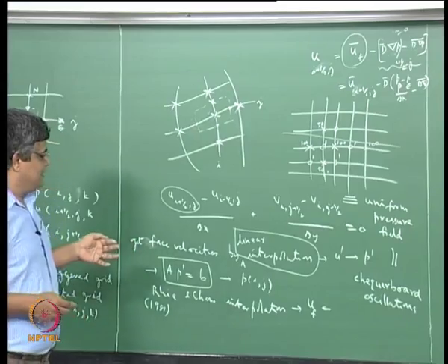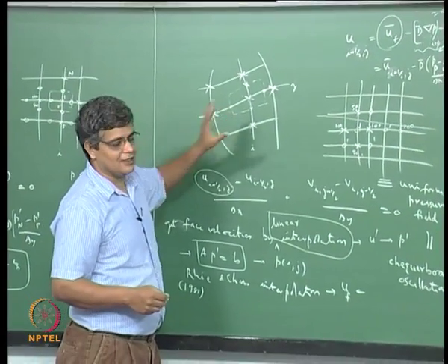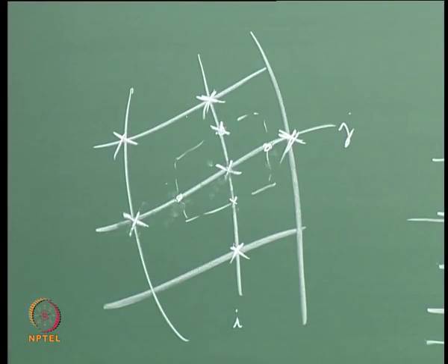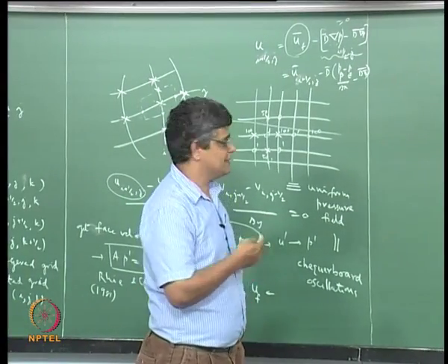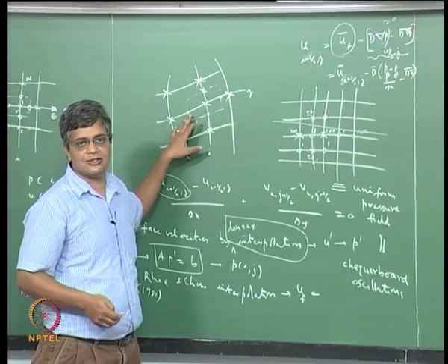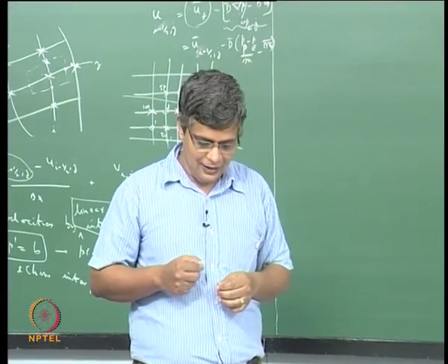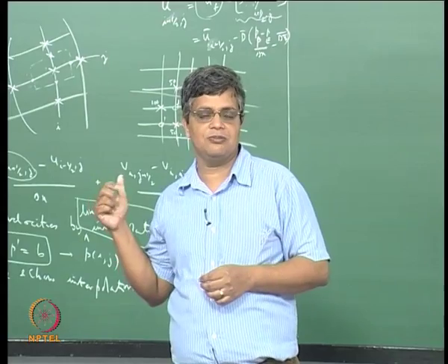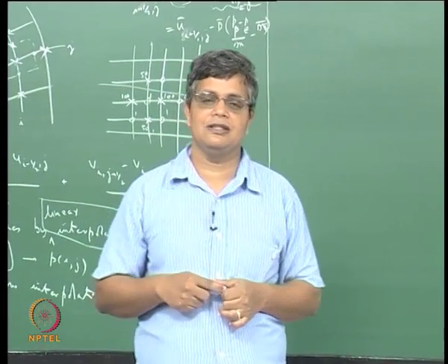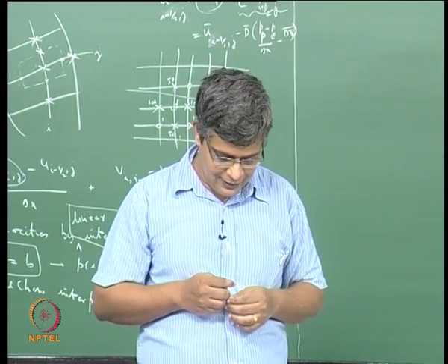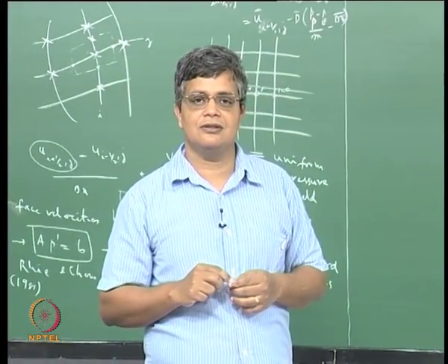Now the question is, we understand how this can be done, at least we can guess how this can be done for the case of structured grids. Now what do we do for the case of unstructured grids? Because even in unstructured grids one can face the same problem of having to determine the phase velocities, and one has to also understand how we can extend this. Actually the extension of this Rhie-Chow interpolation algorithm for the determination of the phase velocities is relatively straightforward in the case of unstructured meshes, and a very similar approach to this can be used.